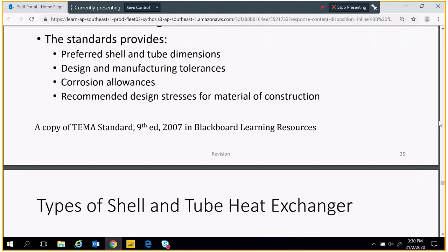So I strongly suggest that you study the MST questions and look at the answers. You see what mistakes we can avoid. You need to be very careful, especially with fluid flow. If there's a T joint and that particular T joint is connected to the pressure gauge, remember there's no fluid flow to the pressure gauge. Therefore, please don't consider the hf for the pressure gauge. Okay, that's for the T joint. So there's only fluid flow through the pipe.